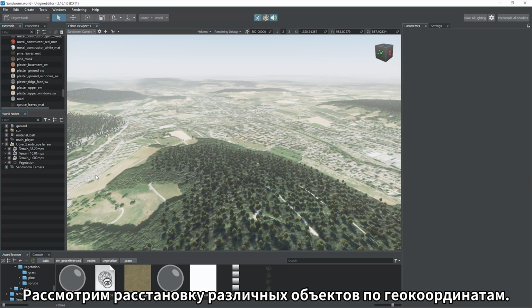You can also fine-tune the masks to filter out certain decals only. Similarly, grass can overlap roads. You can take advantage of intersection tests between objects by specifying a common bit for the cutout intersection mask of grass nodes and the intersection mask of road decals. This ensures that the grass will be cut out in the areas under the road. To learn more about bit masking, watch the corresponding video tutorial.